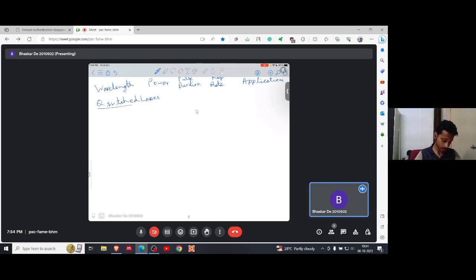Now I will write the wavelength, the first is 1320 nanometer, power is 0.4 to 1 watt, pulse duration is 5 to 20 nanosecond, repetition rate is 2 to 20 kilohertz.